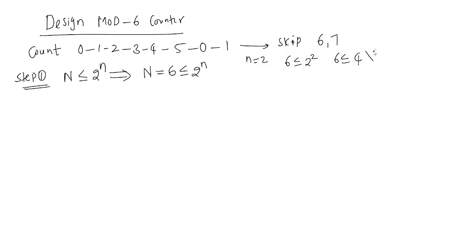Is this condition satisfied? No. If you take 2 cube, 6 is less than or equal to 8. Now it is correct. So 3 flip-flops are required now.